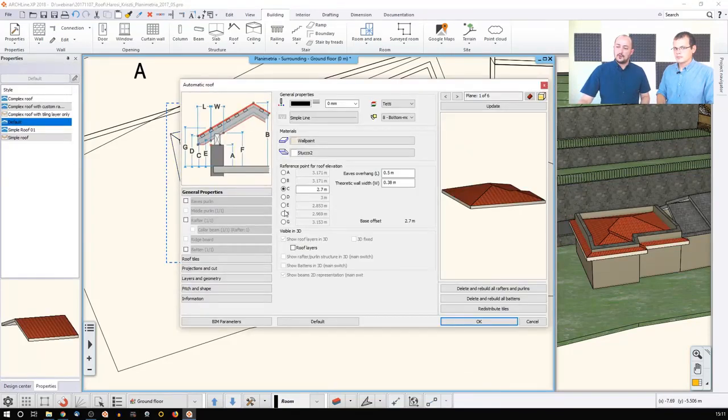Now, first things first, if I go back to change the settings, I can set up the position of the roof. Like, for example, I can tell where the wall height is, what I can see from inside. This is value F. I can say where the bottom part of the roof is. That's value C. As you can see, when you click on any of those, you can determine that value. And the reason why the rest is grayed out is because once you determine this, it determines all the rest. So you only need to know one of those, and everything else is sort of updating automatically.